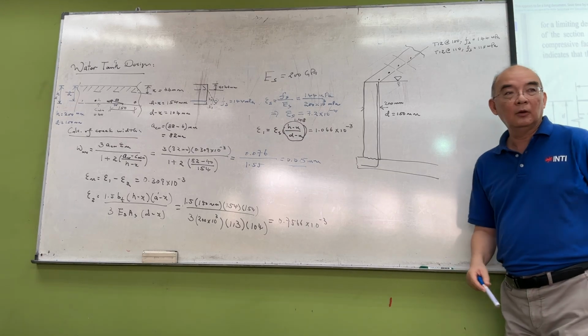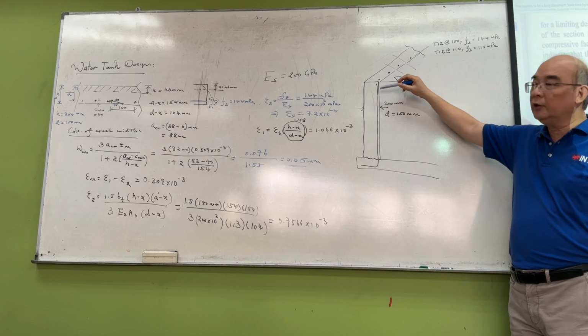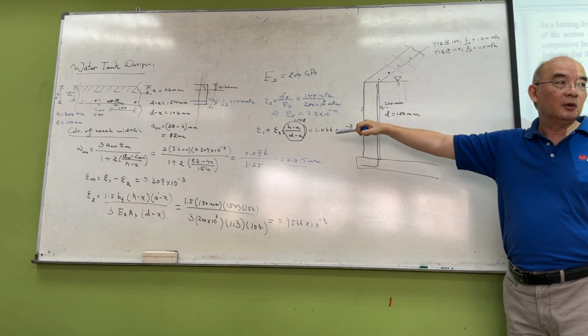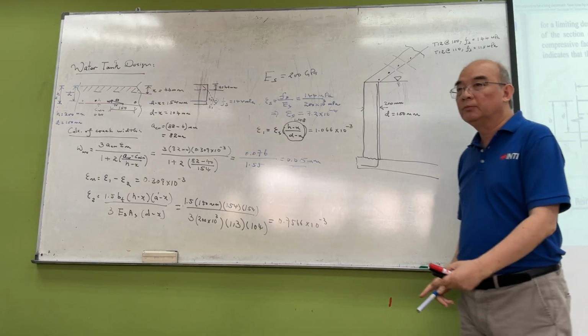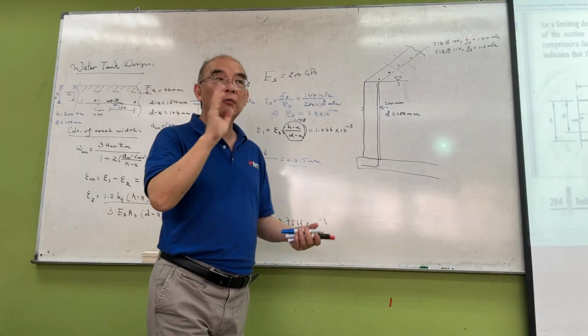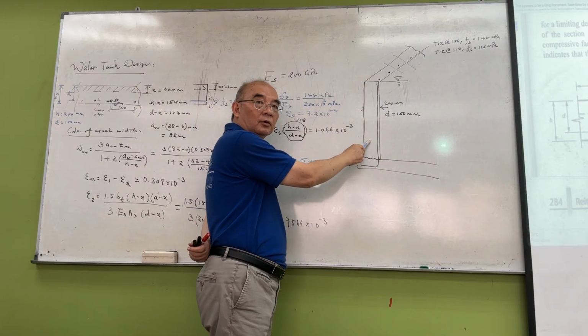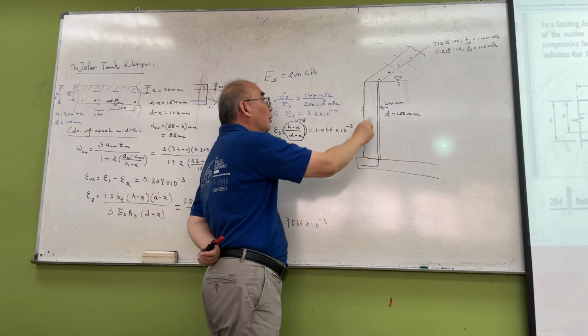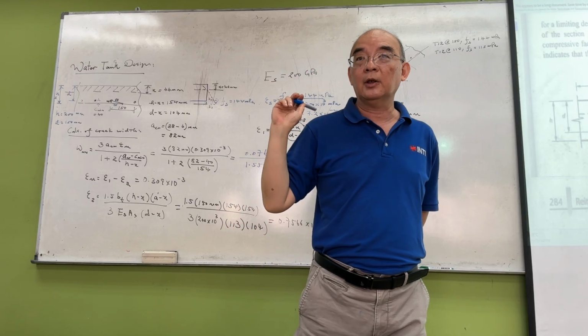So let's repeat. This is the vertical load that we need to resist the overturning moment from the lateral water pressure. Now, if you look at most of the walls, they will have 2 layers of rebar, and also horizontal rebars. We have not covered that.